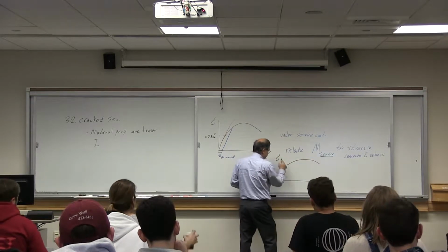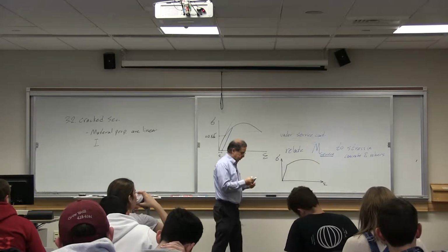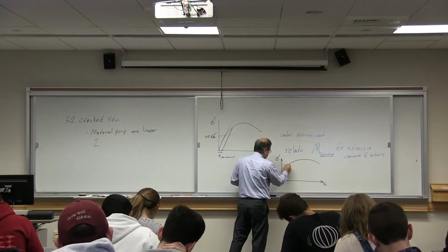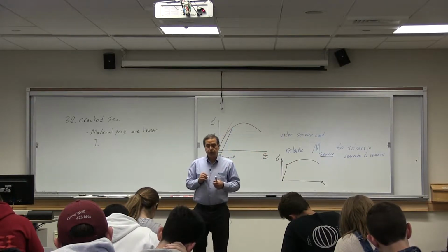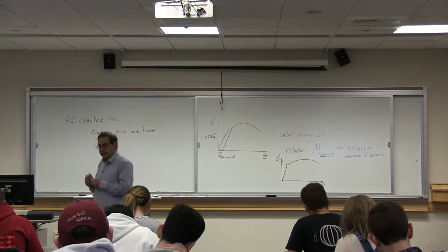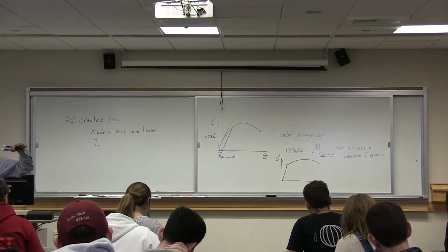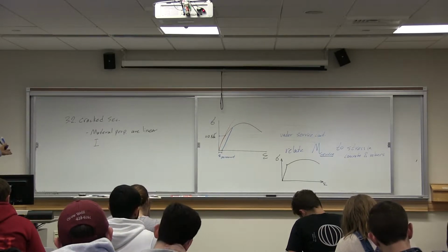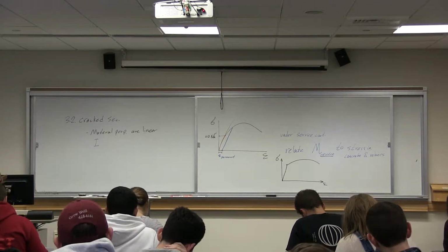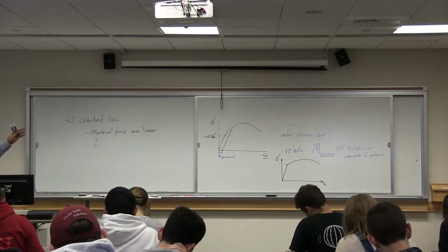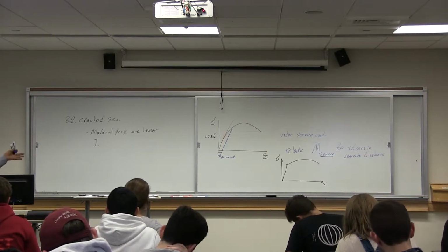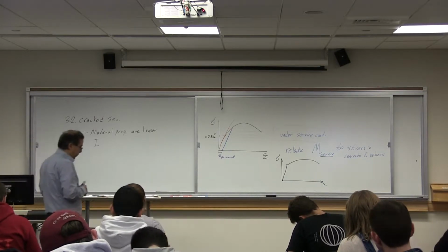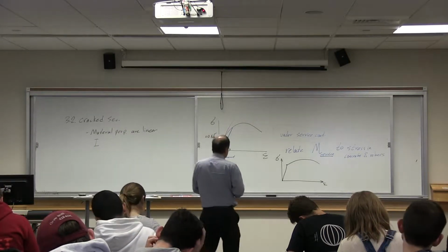This is the stress-strain relationship for rebars. The suggestion is to limit it up to here, which makes sense. One, up to that point, steel is linear. It satisfies the requirement we wanted. From a damage point of view, if you pull the rebars up to the yield stress, let it go, there is no permanent strain. So it satisfies both requirements. That's a good limit to start with.